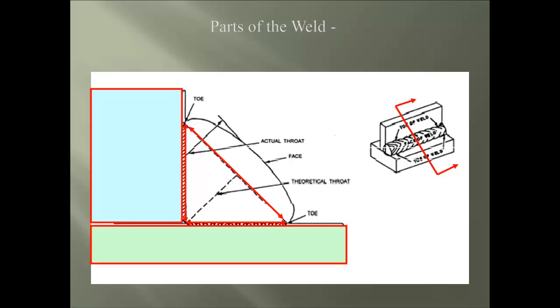So now the fillet weld size is determined by the length of each weld leg. So measure the vertical leg at what is called the toe, and then the same location of the horizontal leg. And whichever leg is the shortest will be the weld size. Now in some cases you could be using an uneven fillet weld that will have you measuring each leg separately from the other.